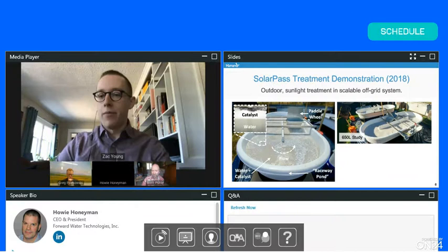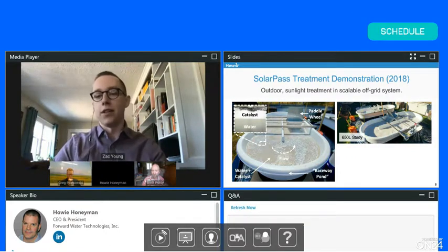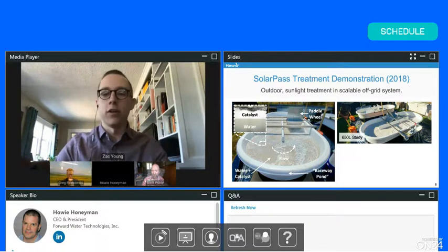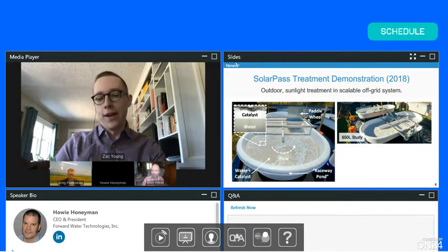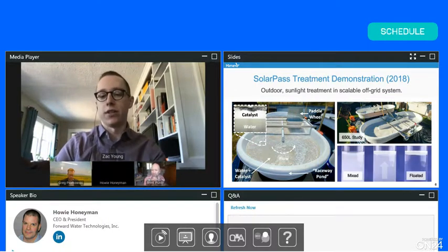The images here are from our 2018 demonstration, giving a window into what the scale-up process looks like. We've gone from beaker scale to an indoor tub under some UV lamps to this being about a 600 liter demonstration study, with 2 parallel reactors able to study the treatment versus control, and do so on 3 different OSPW sources. You can see on the left some images where I've shown the catalyst as it floats on the surface of the water. In our mixing process there, we're using a low-power paddle wheel mixing to gently move and bring the contaminant to the surface where it is treated. And you can see in the bottom right an example of what that flotation process looks like for our treatment material.